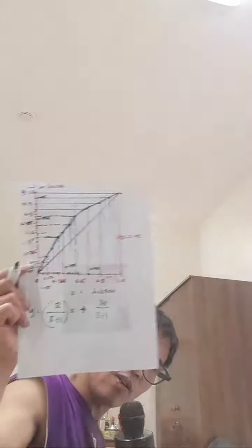This is a mole fraction generally. So usually this is a rectifying line, so this is understood to be the feed. Plus, it's going to be the XD. Okay, XD over R plus 1. It doesn't make sense, guys, right? Let's analyze on the spot. If we have XD over R plus 1, then this X beside the slope is also XD to make sense. But the books and the online web pages that I researched have no such declaration that this X beside the slope R over R plus 1 is the distillate.